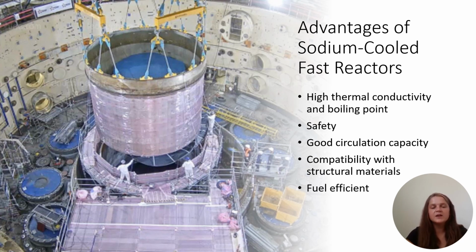One of the main advantages of a sodium-cooled fast reactor is their high thermal conductivity and boiling point. So this results in a couple things. One of those things is it results in a flatter radial temperature profile within the pin and much lower normal operation and transient temperatures. This allows the reactor core to be designed with higher power density without the need to be pressurized.